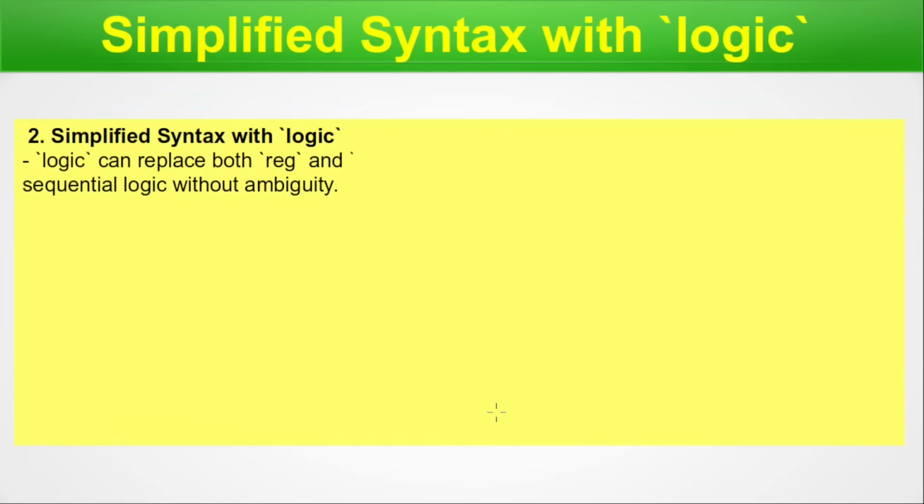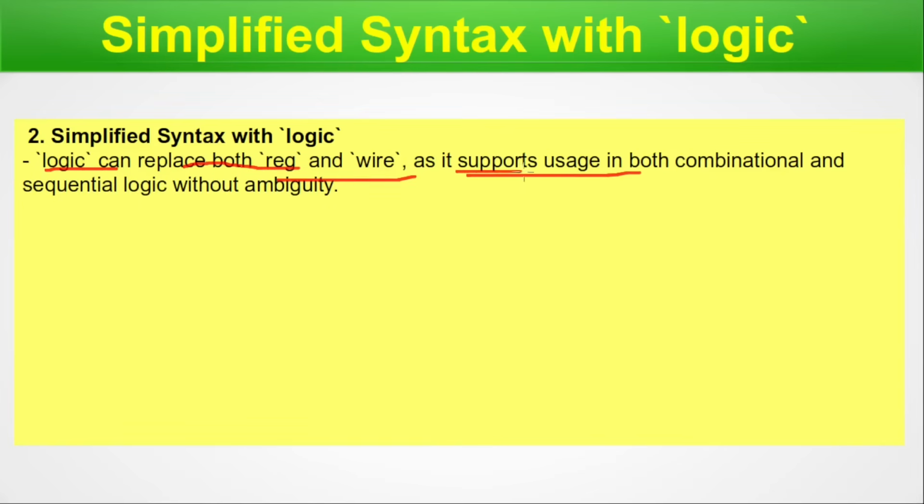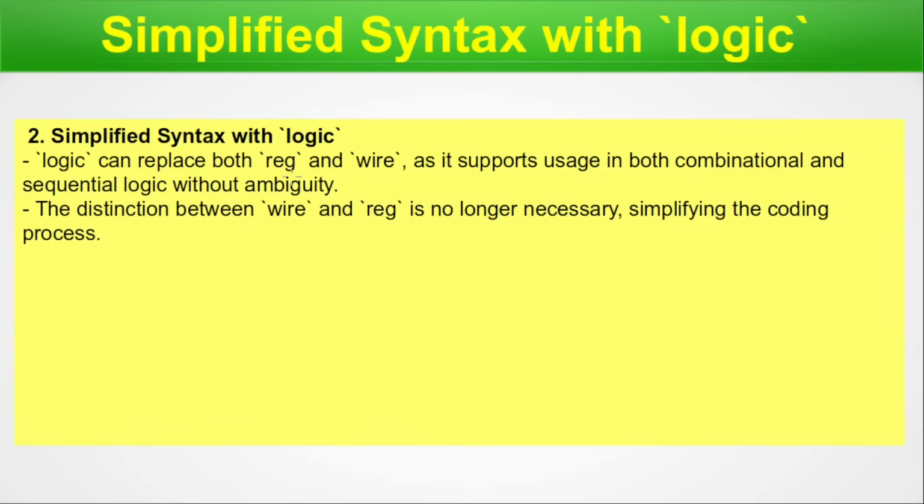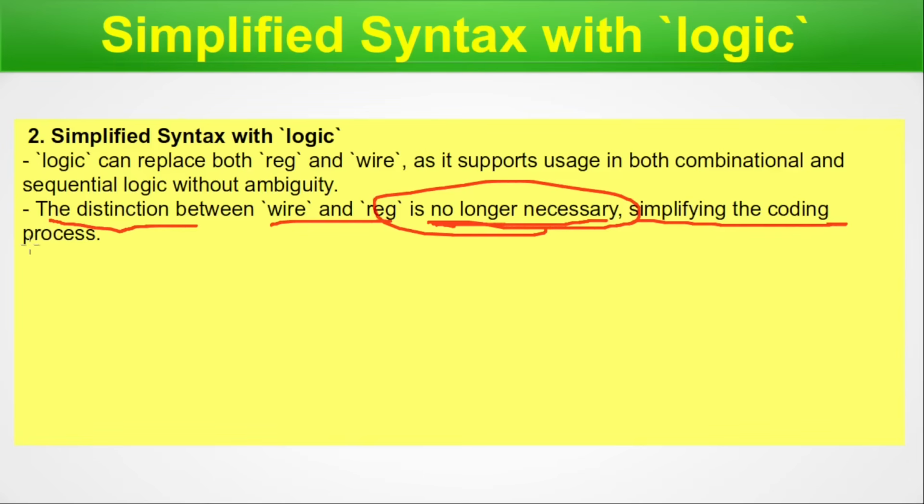Simplified syntax with logic. Logic can replace both reg and wire, as it supports usage in both combinational and sequential logic without any ambiguity. The distinction between wire and reg is no longer necessary. I emphasize, no longer necessary. It simplifies the coding process. Logic does that.